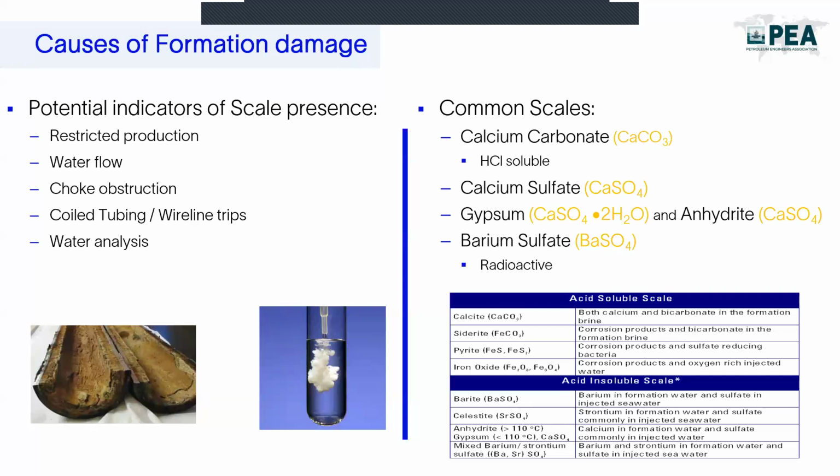And this barium sulfate is insoluble in HCl, and it's really hard, if not impossible, to dissolve this kind of precipitate. So injecting water into our reservoir, either during drilling or any completion, or sometimes even the workover during the well killing process, might create these kinds of scales.